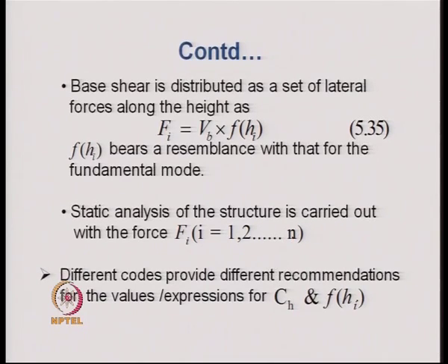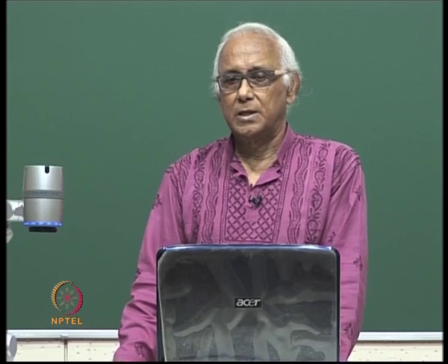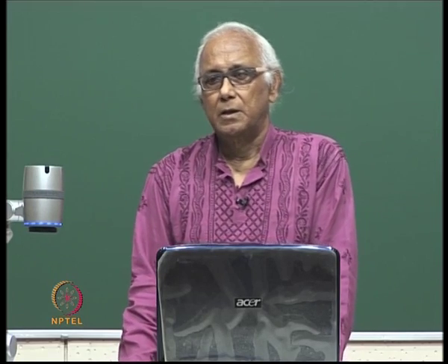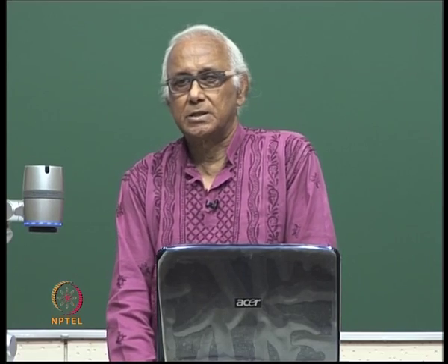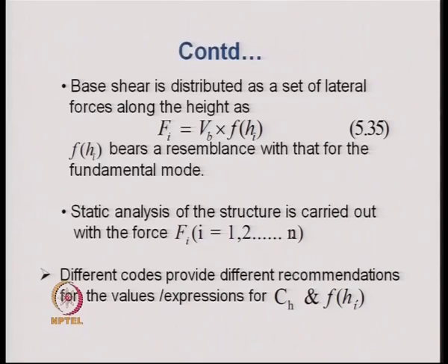It is intentionally done so that under the actual earthquake the structure undergoes an inelastic excursion, and this inelastic excursion is a very important thing for all earthquake analysis of structures, because we wish to design the structure for certain ductility.